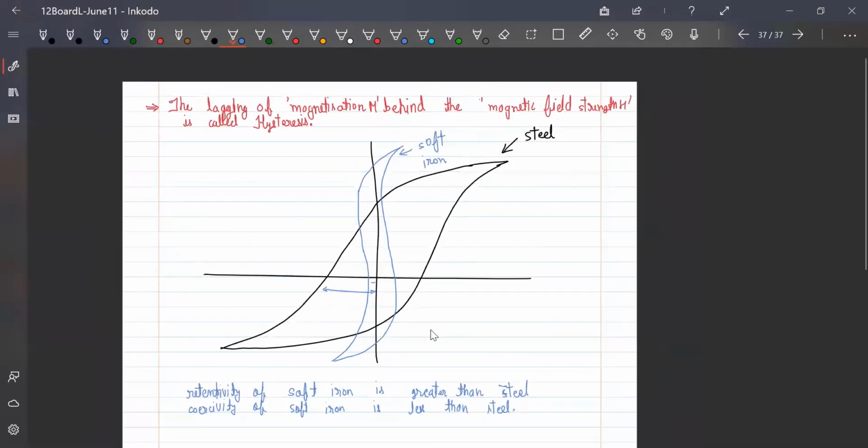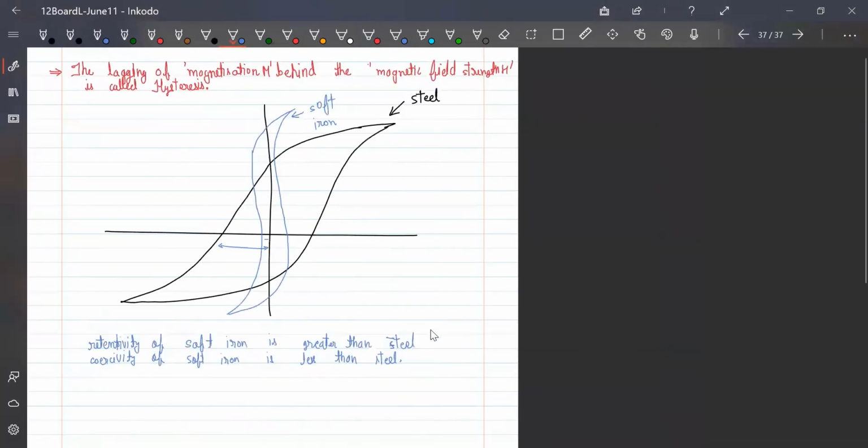And the hysteresis loss is the loss that is due to many cycles of magnetization. In a transformer, once the current flows forward, the magnetic field and magnetization are in the forward direction, then we reverse it, then we again reverse it. So when transformers use AC current, it keeps on going through this loop. If hysteresis is more, the loss will be more, as the magnetic field cannot change immediately. So that's why we use soft iron for transformers and other materials to reduce the hysteresis loss.